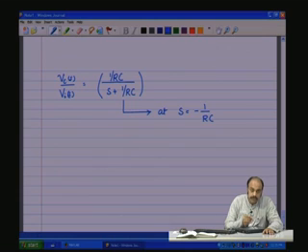So, the gain goes to infinity, and that is a pole, because the roots of all the denominator terms will be poles, the roots of the numerator terms will be zeros. There is no S term in the numerator, so no zeros here for this circuit. You have only one pole, which is located at S equal to minus 1 by R C,